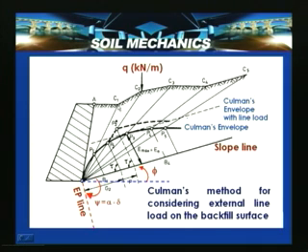Suppose AC1 is horizontal, C1C2 has a certain slope, and C2C3 has a certain slope. Only difference is that here there is a line load or a boundary wall which exerts a load. Now, in a similar procedure, draw the slope line with that phi and draw the pressure line.